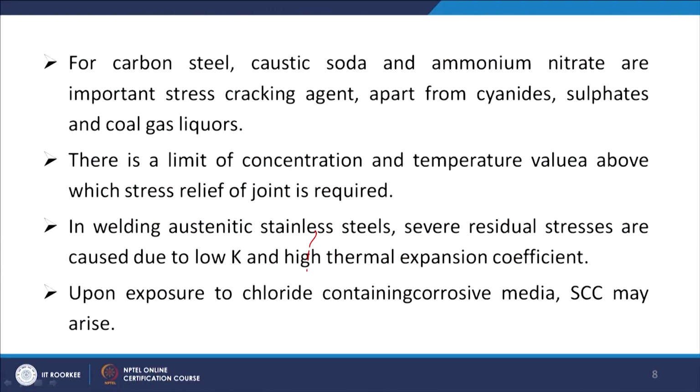That is what we have also seen, that when we are welding austenitic stainless steels, severe residual stresses are caused, and that is because of the property of this type of stainless steel.